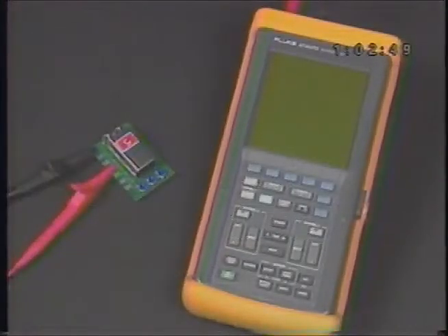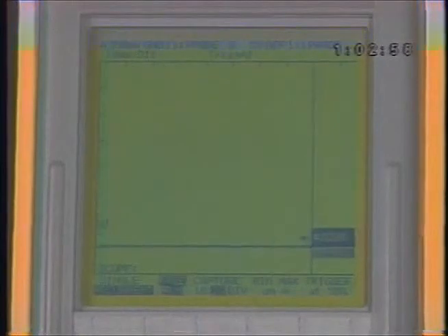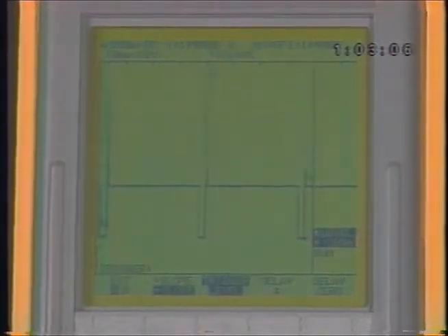Adjust the simulator to the settings shown in the simulator exercise for Lesson 5 in your workbook. Set Scopemeter to display DC coupling with the ground trace aligned with the bottom voltage division. Adjust the trigger level to about 500 millivolts negative slope. That sets the trace to begin with the injector on time.